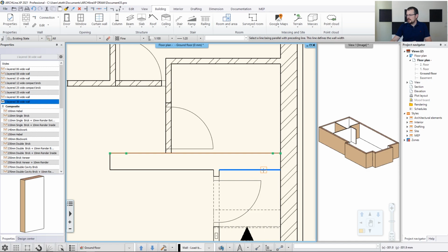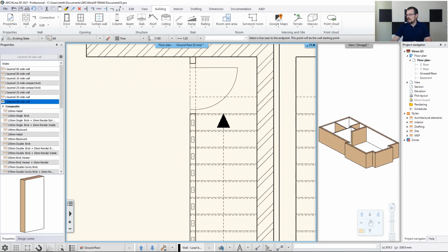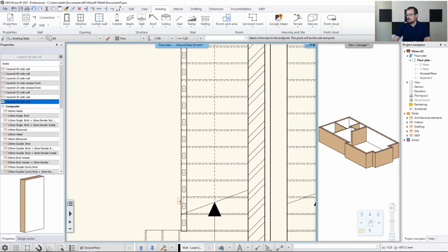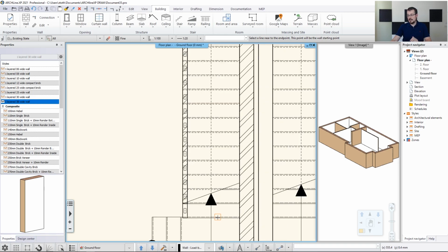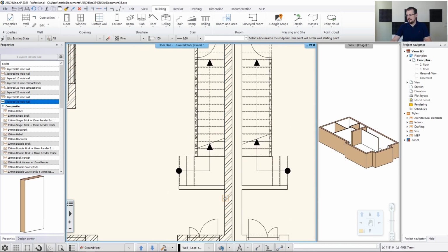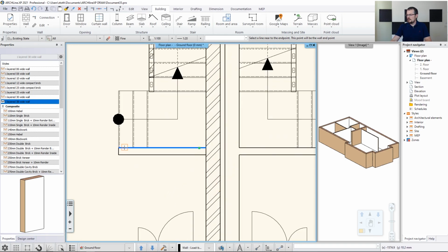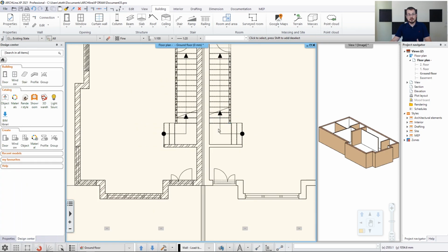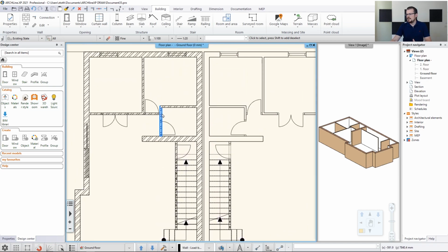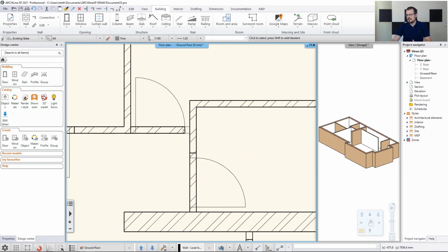And just click on the ending points and the thickness, and then the software would give you exactly what you need. Now, there's going to be one special case over here. I'm making a mistake here intentionally, so later on I can show you how to amend that, how to correct that. So click. Now, I think I have all the walls done correctly, but there are two issues. One is with the T connection over here. There's the connection missing.